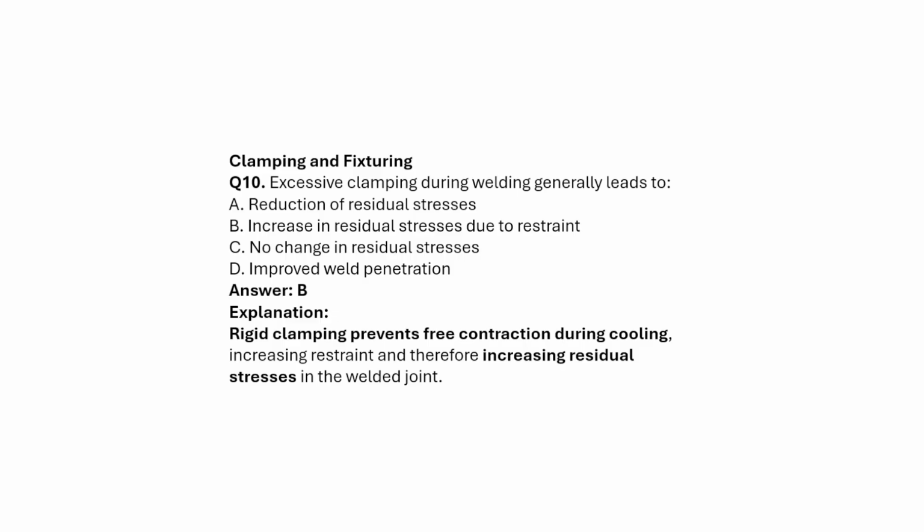Next, excessive clamping during welding generally leads to: reducing the residual stresses, increasing the residual stresses due to restraint, no change in the residual stresses, or improving the weld penetration. Answer will be B, increasing the residual stresses due to restraint. Rigid clamping prevents free contraction during cooling, increasing the restraint and thereby increasing the residual stresses in the weld joint.